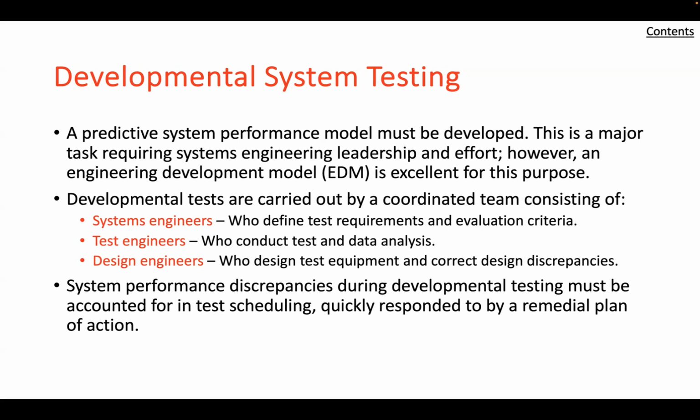So as mentioned earlier, the system test process often requires that essentially all of the system be subjected to testing before the final system has been produced. For this reason, it is sometimes necessary to construct a prototype referred to as an engineering development model, EDM, for test purposes, especially in the case of a very large complex system. An EDM must be as close as possible to the final production in form, fit, and function. For this reason, EDMs can be expensive to produce and maintain, and must be justified on the basis of their overall benefit to the development program.